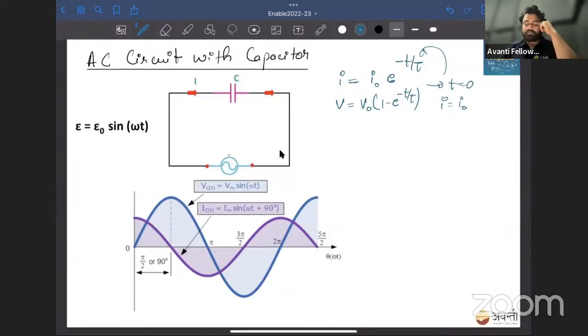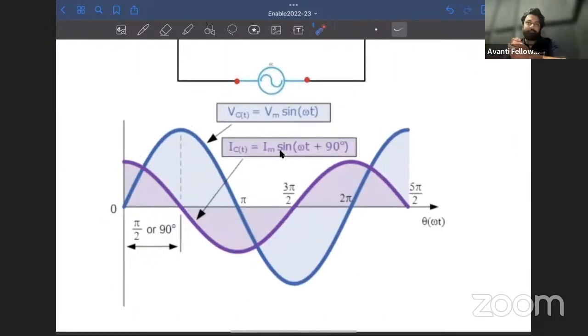Anyways, here also, when this alternating current is applied, the capacitor will show this type of behavior. Let's say this is the voltage curve, a sinusoidal curve. Voltage starts from 0, goes to maximum, then 0, then minimum, then 0. How is current behaving? Just take a look. When voltage is 0, current has some value, and that value is maximum. Then maximum, minimum, maximum, minimum. Clear?